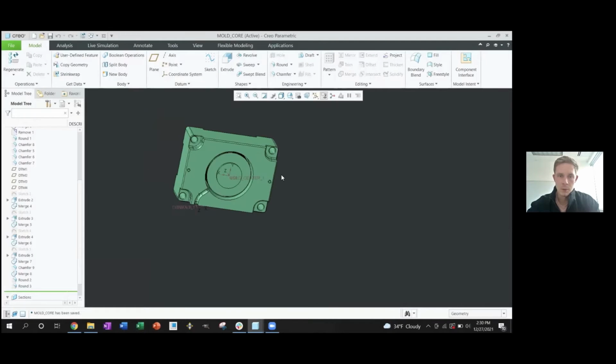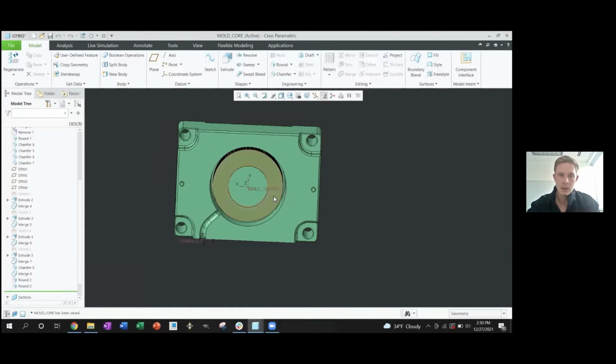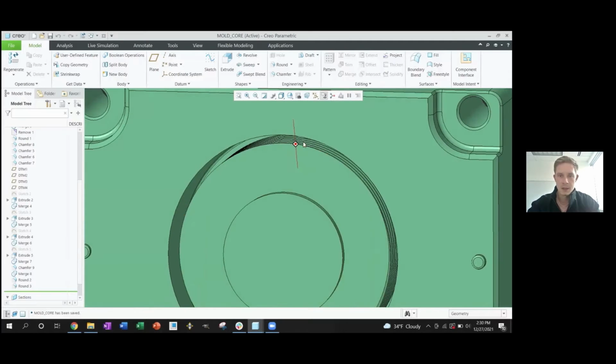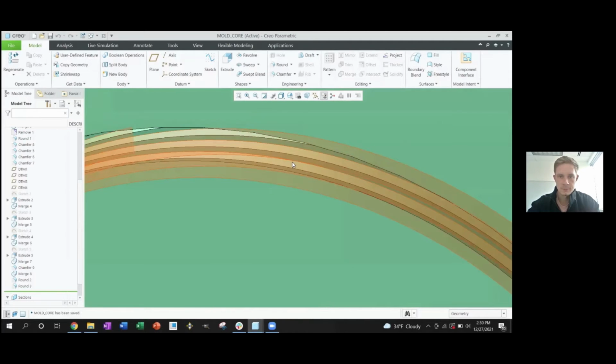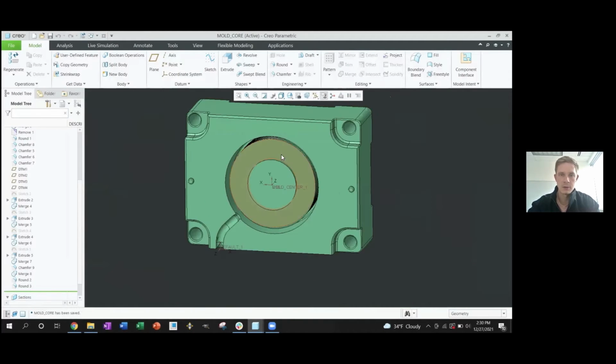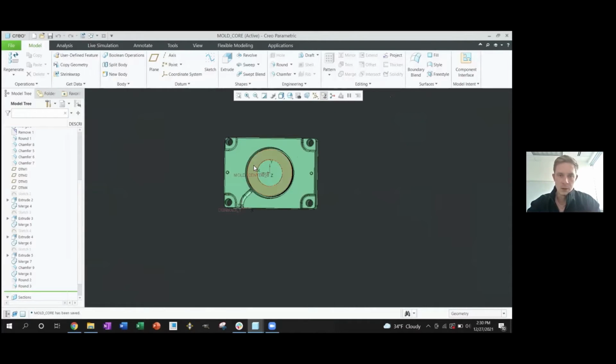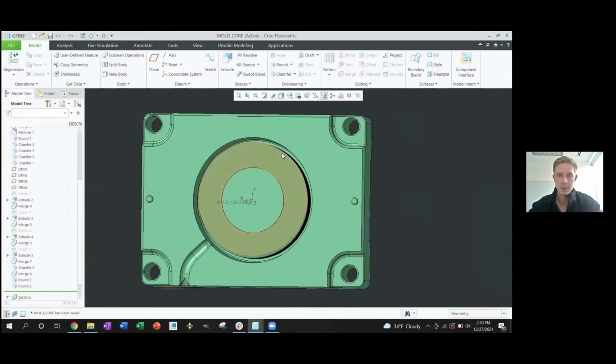So we'll go over to our mold core here. Like I mentioned in module 3, this mold is designed, but you can't actually mold with it. And that's because all the threads on this insert here are undercuts. So this part itself can't be ejected from this core section with just standard ejector pins and a straight pull. We actually need to unthread the part off of this insert.